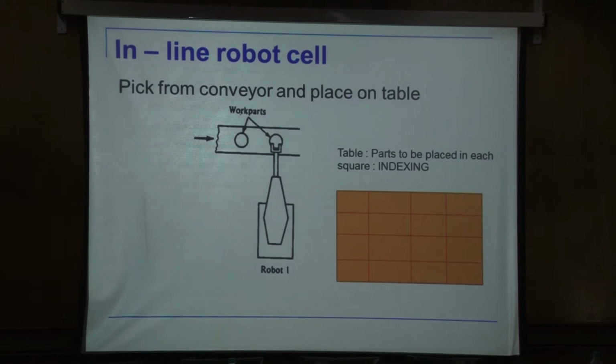So we can also write a program for this one with some sensor interfacing. So in the previous program, there was no sensor interfacing. So we can simply use commands like sensor 1, sensor 2, on, off, and then to indicate when the part has come, when the robot has picked up the part. So when there is a conveyor also, when the part is coming on the conveyor, the moment we can put a sensor here, the sensor will sense this, and the moment the part comes, it can say signal 1 is high. The robot understands the part has come, it will pick it up and put it there. Okay? So that program also can be written, or we can simply add those few lines onto that program.